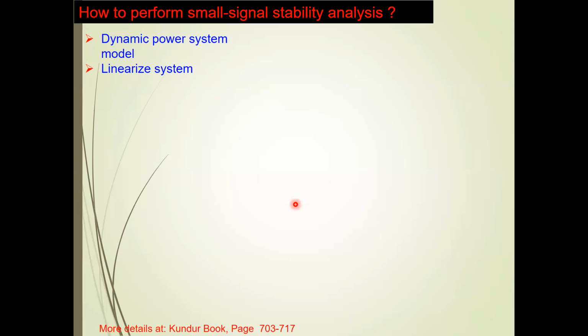And another, let's say the line is represented by an impedance. It is the series combination of resistance and inductance, and you can even consider the capacitance as shunt. But the resistance, inductance, or capacitance of the line are static. The parameters will not change, and thus it is static. So the line is also a linear model, right? The transformer can be a linear model. What about the load?